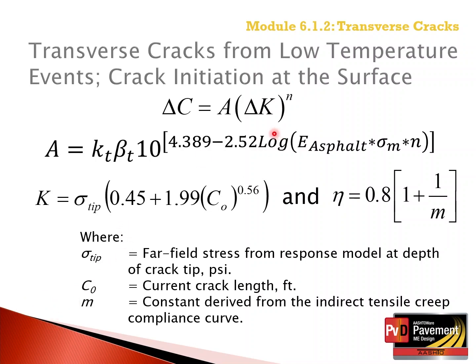So the stress intensity factor is defined at the crack tip based on the far field response model at a depth of the crack tip in PSI, and it's a function of the current crack length or crack depth, and N, the fracture mechanics parameter, is a function of M, which is a constant derived from the indirect tensile creep compliance curve.